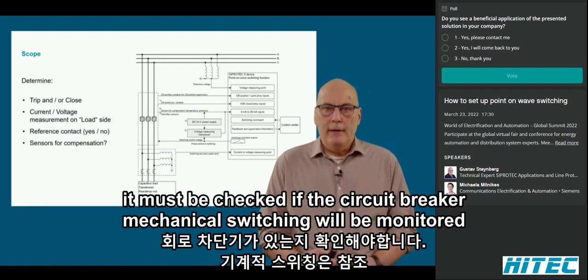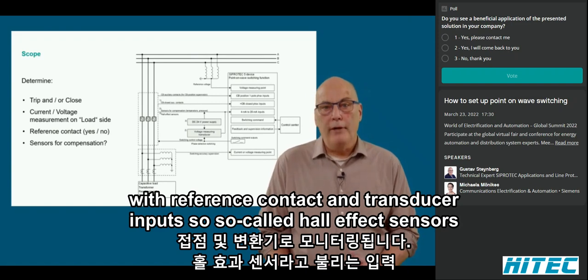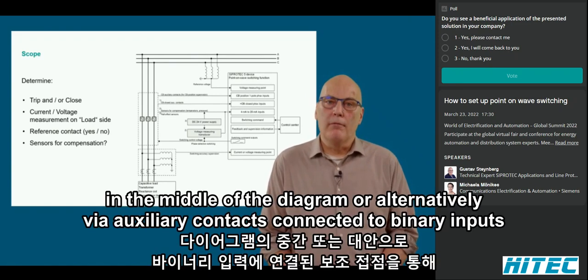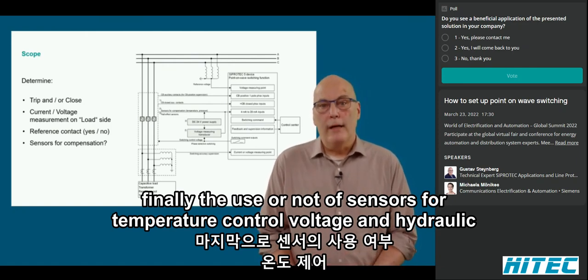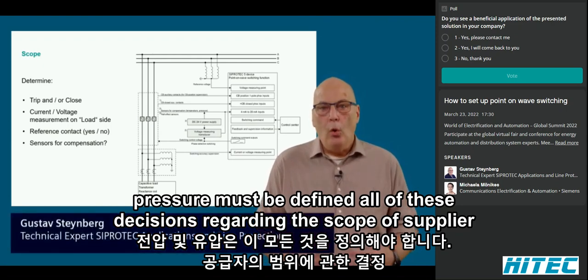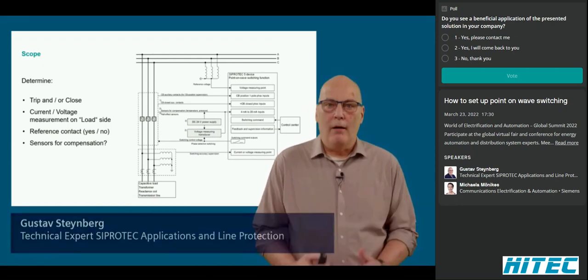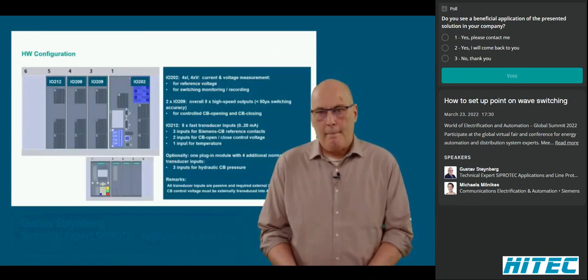It must be checked if the circuit breaker mechanical switching will be monitored with reference contact and transducer inputs, so-called Hall effect sensors, in the middle of the diagram, or alternatively via auxiliary contacts connected to binary inputs. Finally, the use or not of sensors for temperature, control voltage, and hydraulic pressure must be defined. All of these decisions regarding the scope of supply are finalized. The device may then be selected as shown in the next slide.